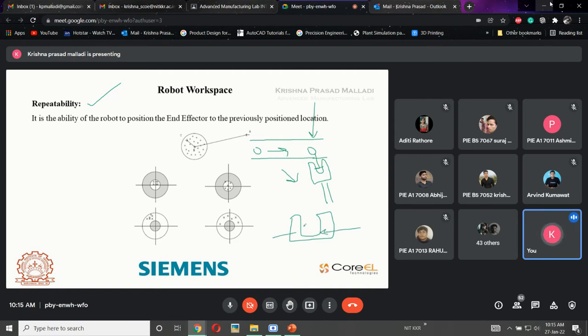In the sliding grippers there is a gap of some 50 centimeters. This part is only 20 centimeters. Now the robot will come like this. This is my gripper, and this is the conveyor. If the part is here, the robot will reach and close. Wherever the part is in this zone, the robot will pick it, which means for picking a part, accuracy does not matter.